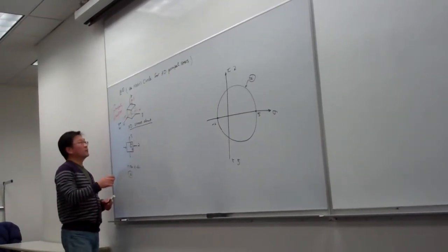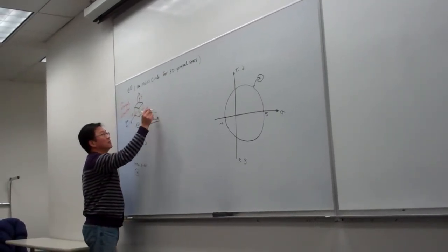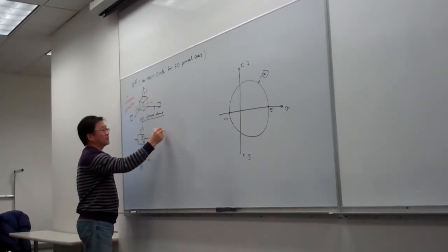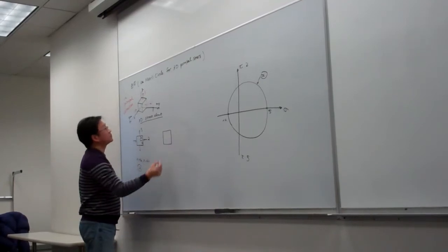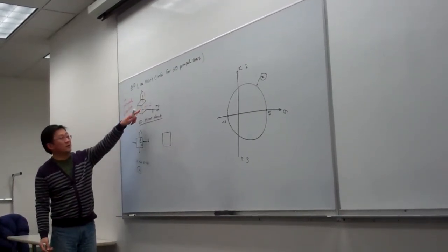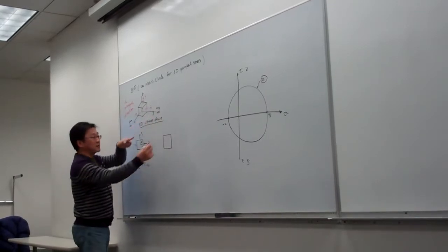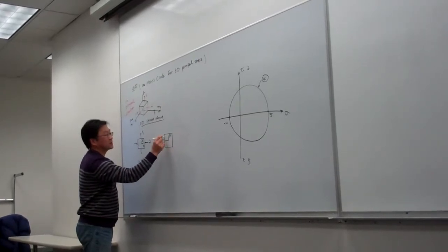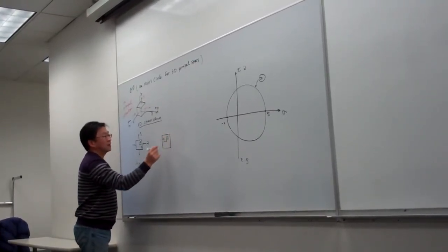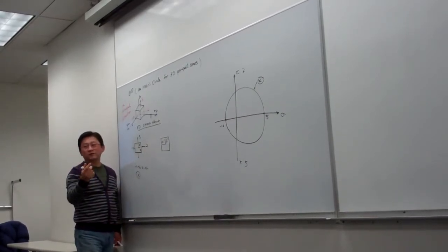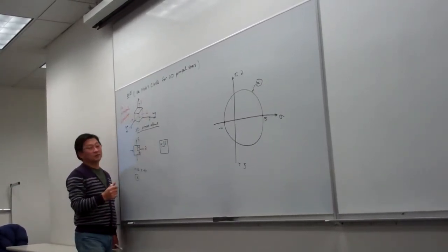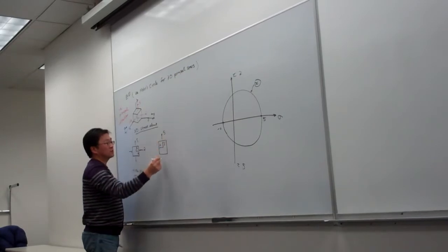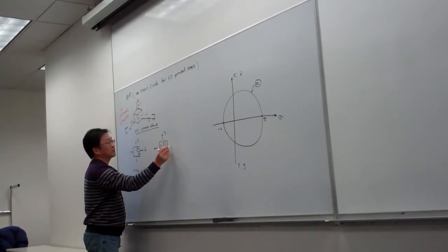And now we change our viewpoint. For example, we change to sitting on the y-axis and looking into that element. So the second viewpoint in front of us is this. Again, looking into the direction in the way we designate. So here is the z-axis, and here is the x-axis. At this moment, don't care about the right-hand rule. We just draw whatever we see. So the x-axis will be here, z will be here. In the z direction, we have the tensile normal stress 5. In the x direction, we have 10.